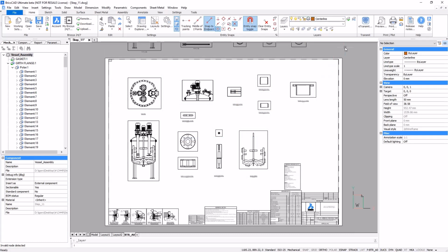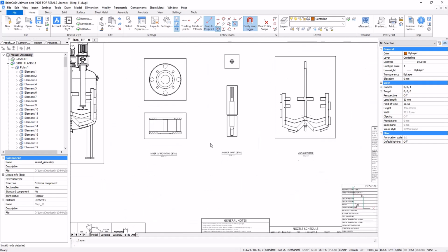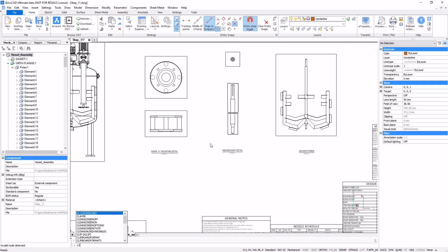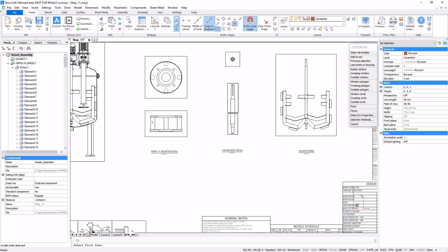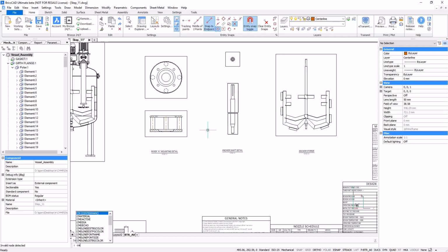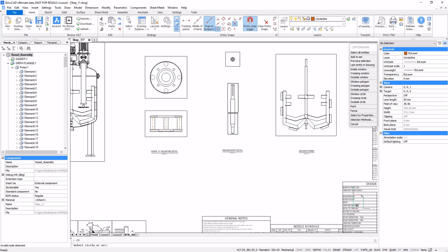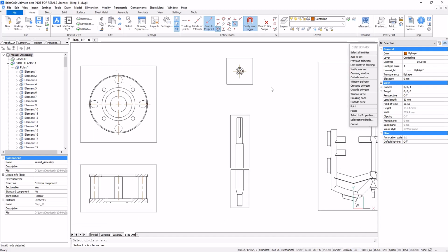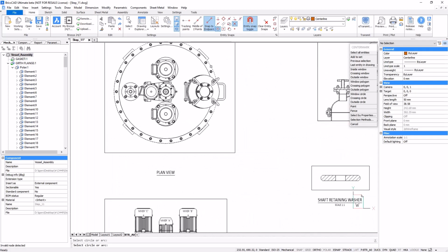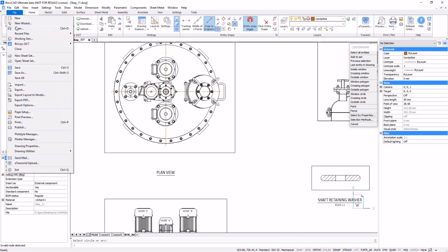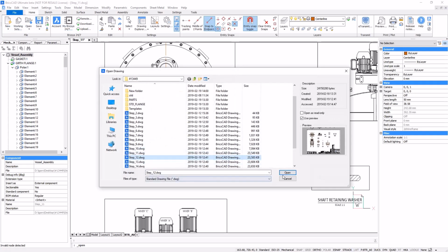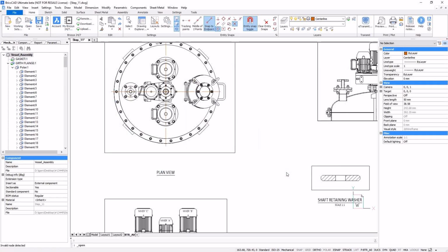Since everything is in .dwg, we can export this particular layout to .dwg, because there are cases wherein you might not want to transfer or share your 3D models. What happens after you export is that the entire set of entities placed in your layout, for example text, mtext, dimensions, the bill of material table, balloons, is maintained as it is, so that in case you want to edit something in the 2D layout, you'd be able to do it.